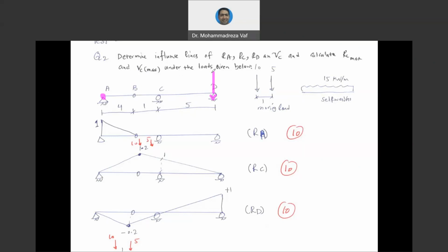Therefore, the deformed shape is going to look like the one that I draw here, meaning at point C we reach 0. Point B is going to go down the moment that we impose the unit displacement to point D. And then at point A, again, we reach 0. So this is going to be the values for the important points of the influence line at point D. Okay, so you can see it was not too much difficult through the qualitative approach to draw the influence line.